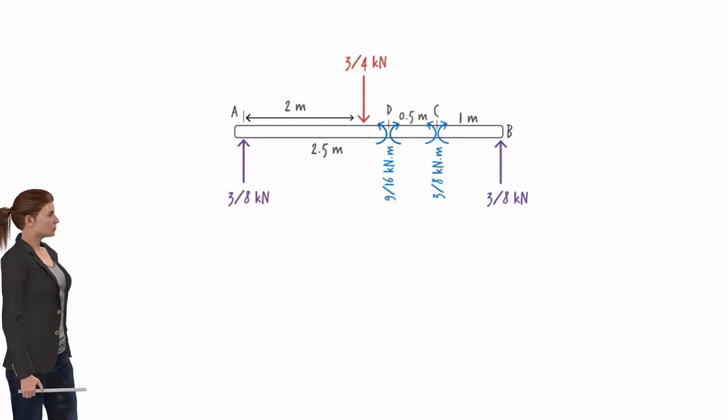In addition to bending moment, beams carry another internal force. We call it the shear force. It is a force parallel to the cross-section of the beam. To see why shear develops in a typical beam, consider segment CD. It is subjected to distinct moments at its left and right ends.